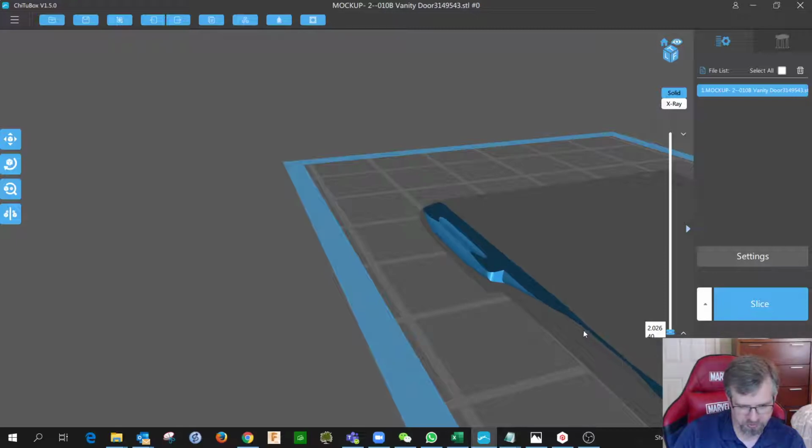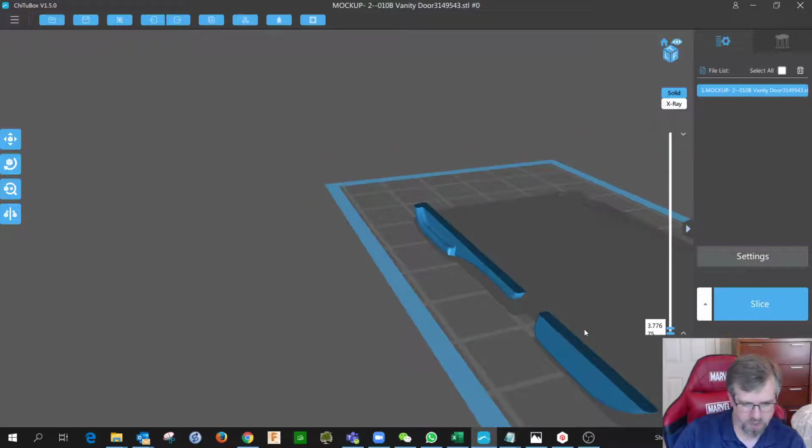By the time you get to this third one, now that's a big bridge, so I don't think so, but as it starts to connect in here, you might be able to suck that part back off, but chances are it's too late, and this whole area is just going to fail for the rest of the print. And what that will result in is there'll just be a big vertical void there.